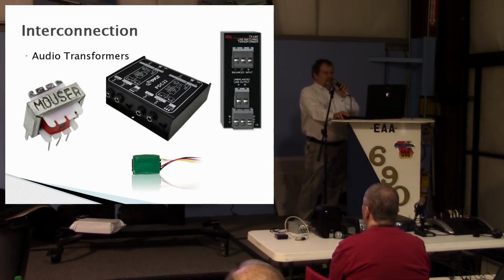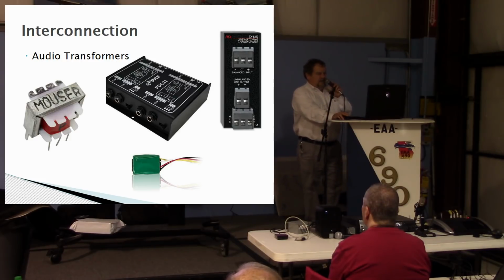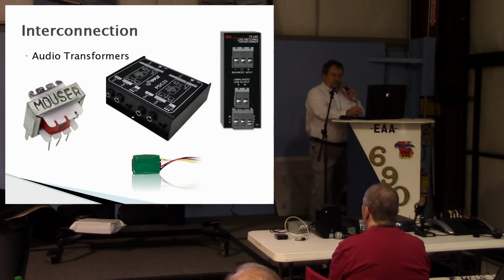The nice thing about these is you can use it to isolate a balanced to an unbalanced, a balanced to balanced, unbalanced to unbalanced, or you can go balanced or unbalanced to microphone level. It's a switchblade. It just depends on how you wire it. One little transformer, and these are push terminals, it looks like. The ones I have are screw terminals. They come in all different flavors.